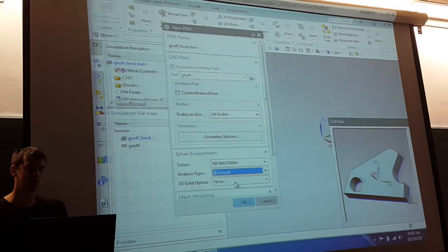Okay. So we want to automatically create our mesh collector, and we want to associate a solid property, or material property, with that mesh collector. So for this mesh, we associate this physical property type, which is PSOLID, that doesn't change, the default's fine, and we want to associate this particular solid property.